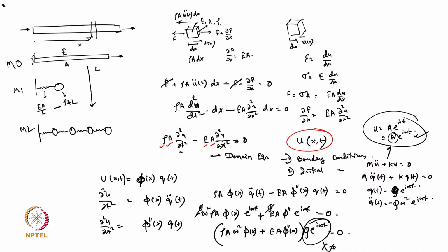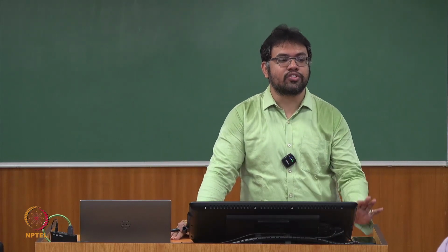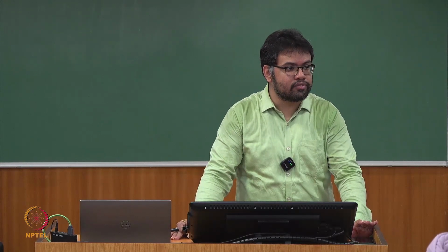I think you remember that. We have to do the full modal superposition, and we need to extract first all the natural frequencies, and then we have to do that. So that's the procedure for the free vibration. But here, what we assumed is the procedure for harmonic forced vibration, where omega is the excitation frequency. Okay? Agreed, all of you?